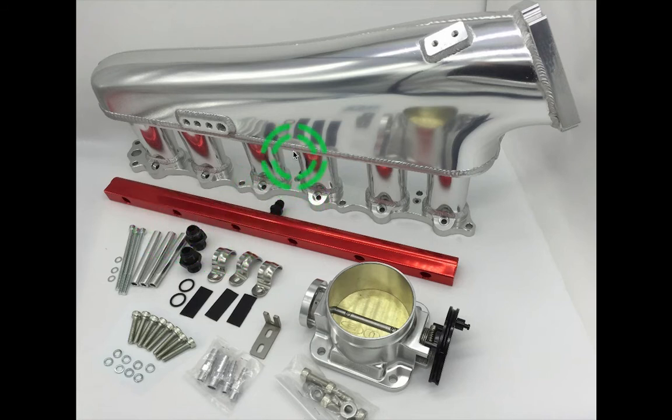But remember, the cheap intakes are not really good, because they don't care about how it is, and the port could be big here and small inside because of welding in such a way. Your nightmare could be if this port is not the same size as that port, so this one is getting more air than the rest of them. Obviously you're gonna be injecting fuel equally to all the cylinders, right?